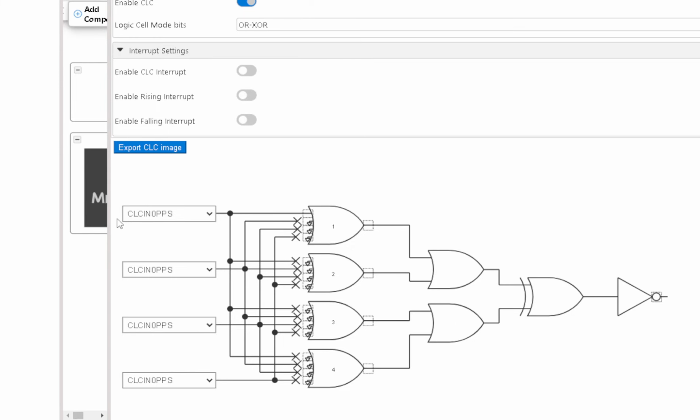You could write a converter if you wish to pull the code in automatically, but essentially find the CLC code you need, extract the initialization out. The rest of it is not important, by the way. Extract the PPS to make sure it matches what you've designed in the configurator, and paste the code in. Job done.